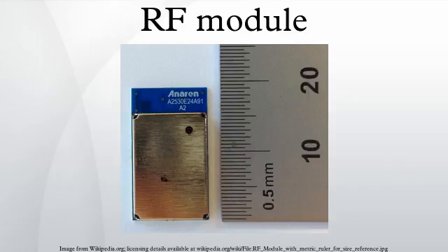Several carrier frequencies are commonly used in commercially available RF modules, including those in the industrial, scientific and medical radio bands such as 433.92 MHz, 915 MHz, and 2400 MHz. These frequencies are used because of national and international regulations governing the use of radio for communication. Short-range devices may also use frequencies available for unlicensed use such as 315 MHz and 868 MHz.